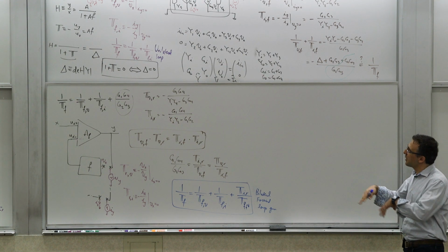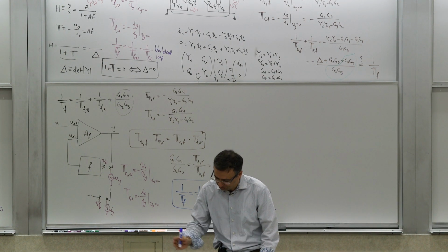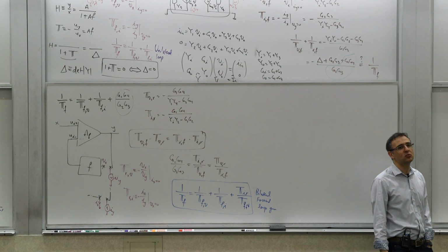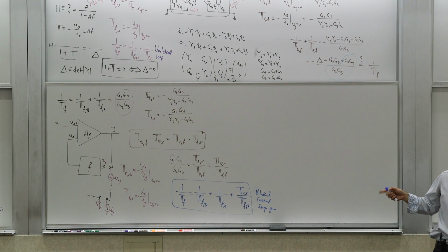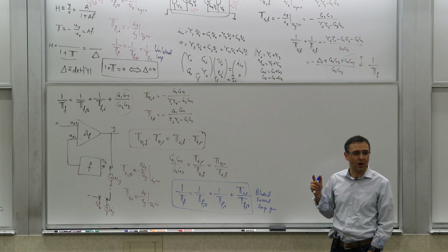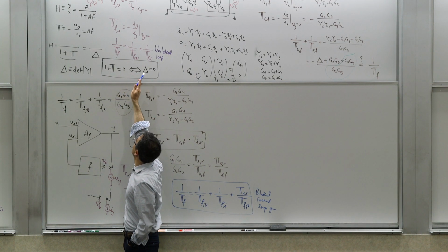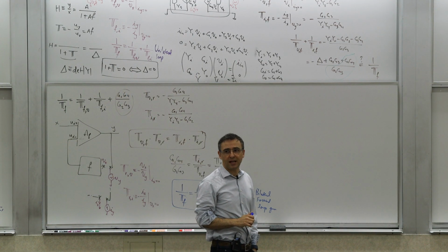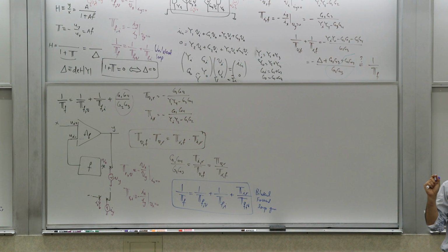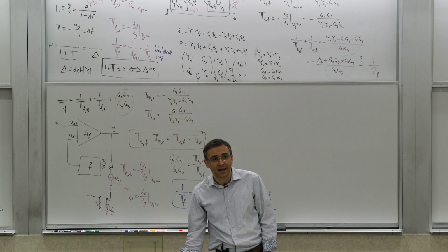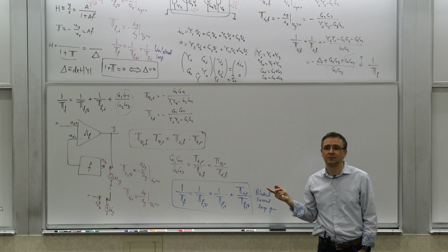Okay, now that was probably one of the hairier derivations that we had. But it's good to know that now you can actually analyze any loop gain forward in general. And this satisfies all three of those requirements that we set. If this loop gain is -1, the roots of 1 plus T equals 0 are the same as the roots of delta being 0, the determinant being 0. So you get the correct poles, always. It's also easy to calculate, and for a simple loop, it's an invariant of the loop. Doesn't matter where you calculate.